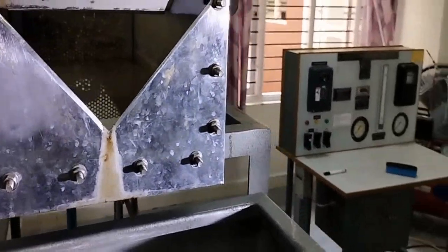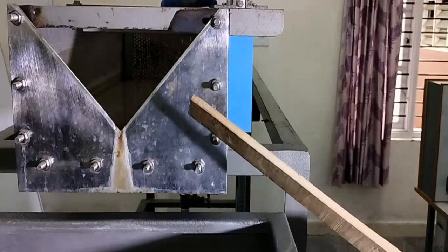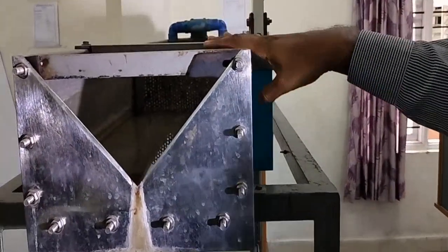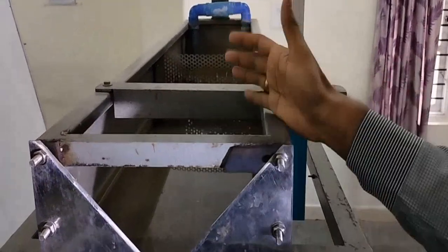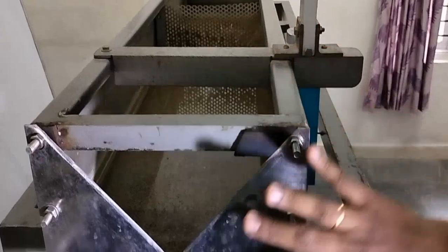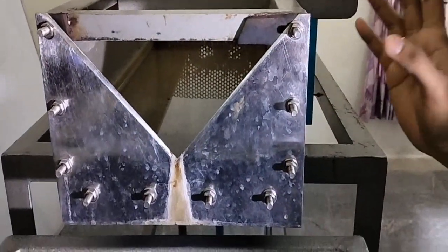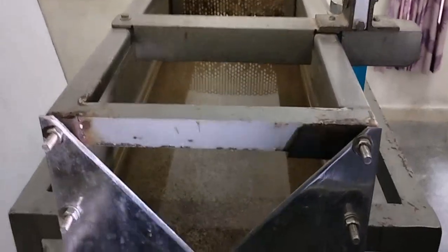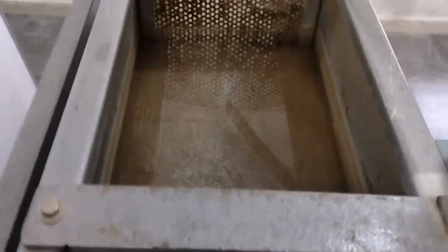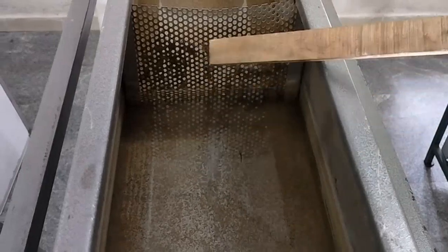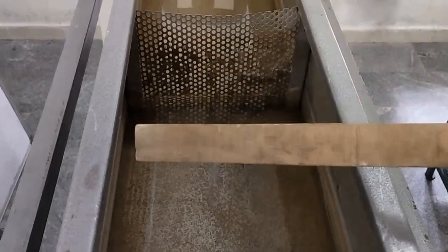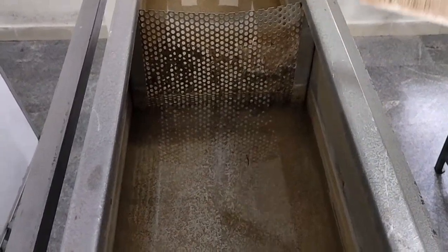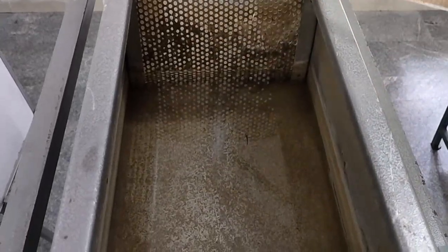Coming to this experiment, the main part is what we call the open channel. This is not a closed pipe; this is a canal-like structure. In this type of structure, we use notches as well as another device called the weir, to measure the flow, especially in open canals. Also, we can see this one, which we call the baffle plate. It is simply used to straighten the fluid and avoid disturbance in the fluid when it is coming from the pump. To make the fluid flow straight, this baffle plate is used.